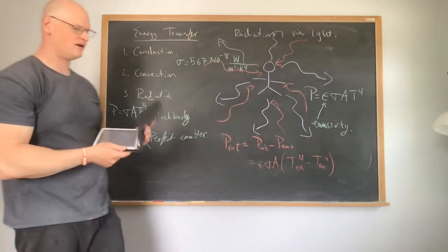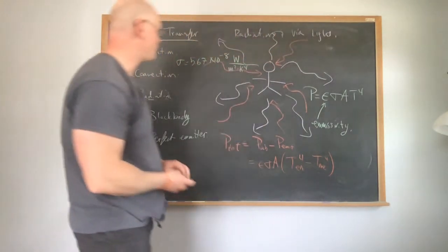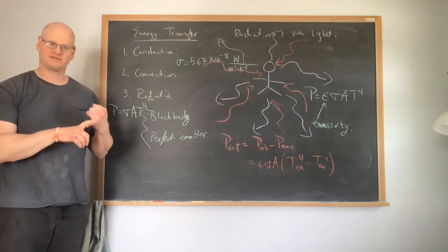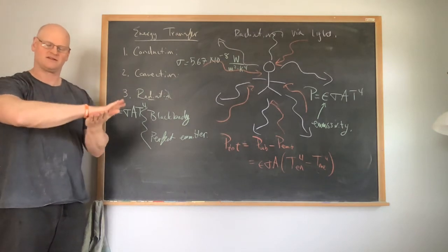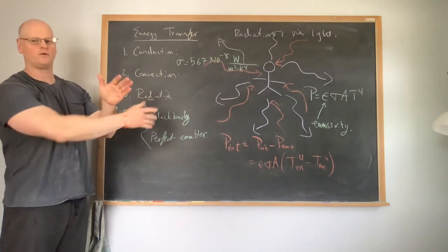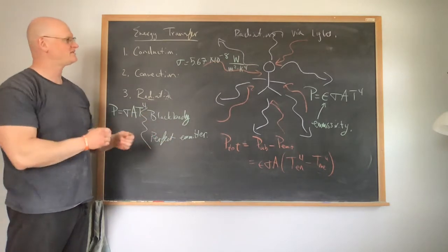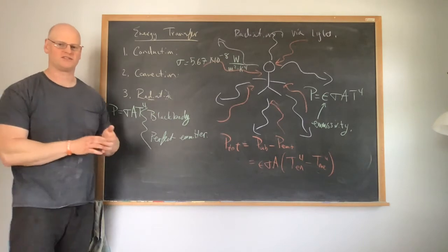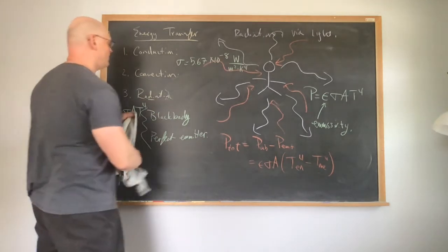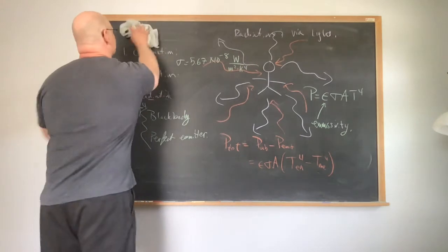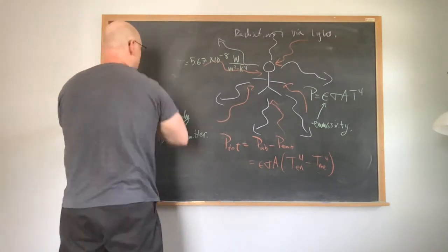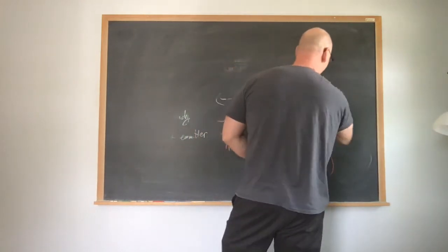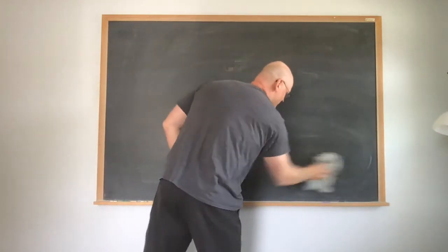So good. These are the 3 ways that we actually give off or can transfer energy from one system to another. Again, we have conduction. Conduction is the direct contact between 2 or more objects. Convection is the flow of the medium itself past an object. And then finally radiation, that is the electromagnetic radiation which is actually given off. Now a good example of putting these together is what's known as a Dewar flask, or simply a thermos. So let's talk about how a thermos is actually designed with all of these things in mind.